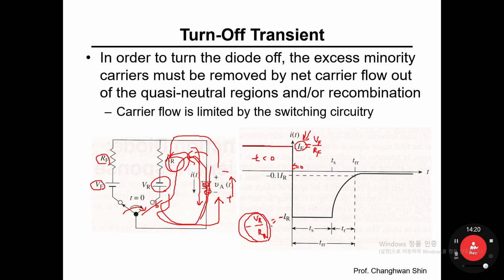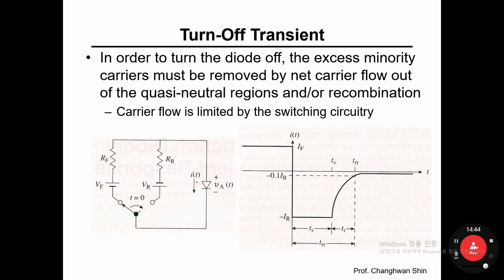Otherwise, it is hard to see and hard to control the reverse bias current throughout the PN diode. But the problem is, even though not because of the excess stored carriers, this PN diode is still forward biased. Forward bias means this PN diode is kind of shorted, right? So right at this time, and maybe from here to here, excess holes and electrons are still moving in this direction.